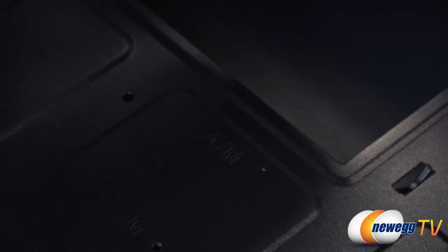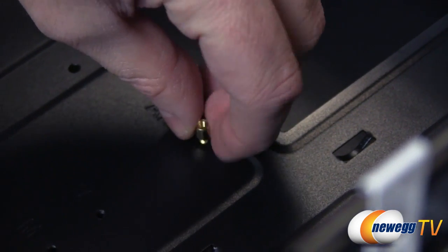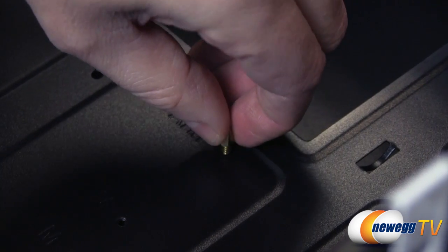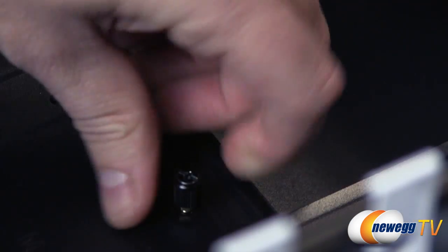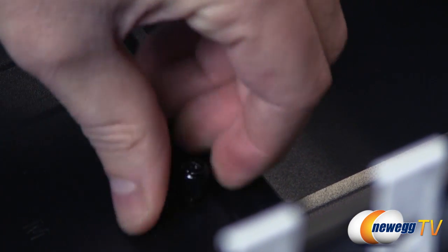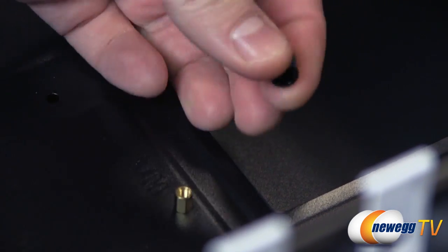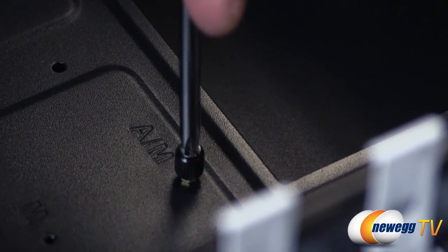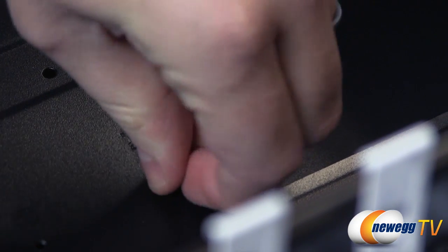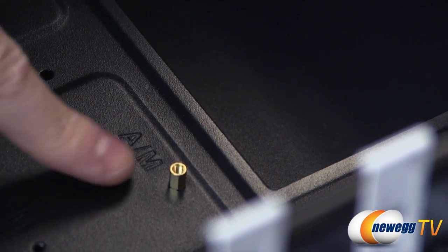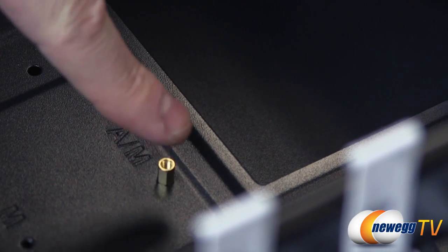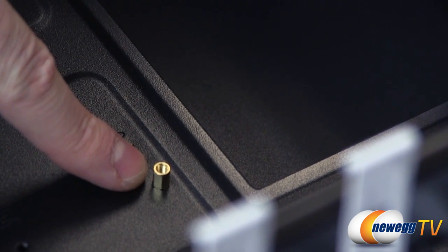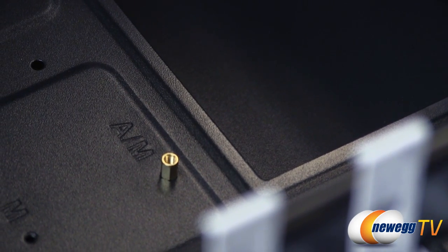And then I'm also tightening these down a fair amount because it's generally okay to make these very, very snug. Do not over tighten them, of course. You don't want to strip the threading in the case. So I'm just going to hand tighten this with my hand, using that handy adapter. And then, oops, gotta leave that on. I will give it another quarter to a half turn with the screwdriver to make sure that that's down all the way and secure. This will make sure that when we install the screws to actually secure the motherboard, if we ever remove it, it won't back those screws off as well.